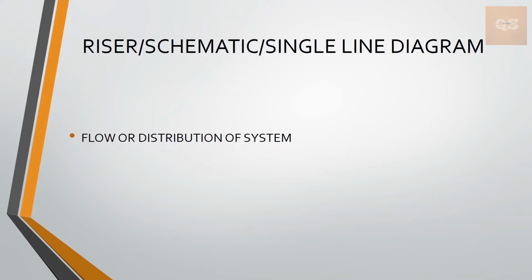There are different MEP risers in buildings through which all these MEP systems pass, the different conduits, bus bars, the duct risers, the pipe risers. So to understand these vertical measurements, these single line diagrams or risers are used. And a single line diagram is mainly an electrical part wherein you can understand how the system is moved, from which distribution board to which part the particular cable moves, and the size and type of that particular cable.